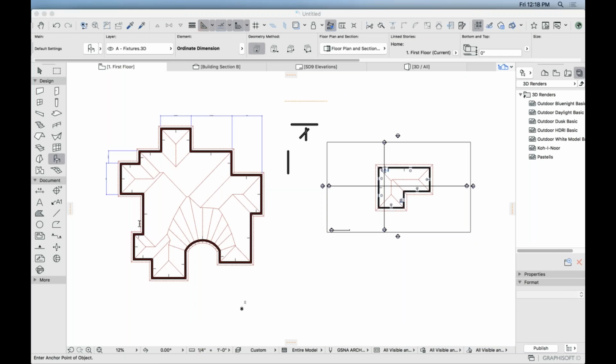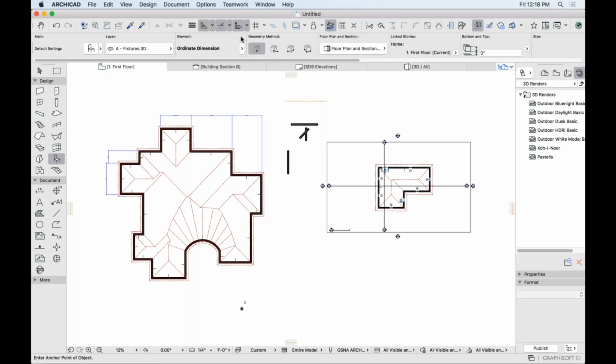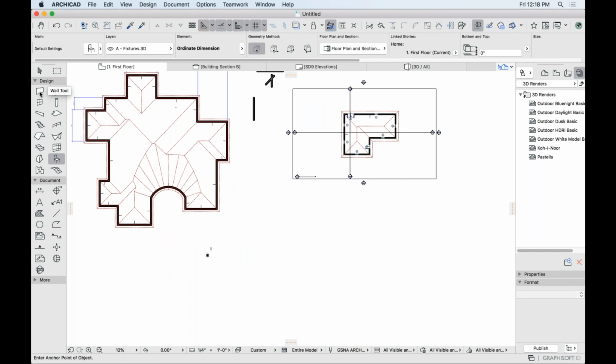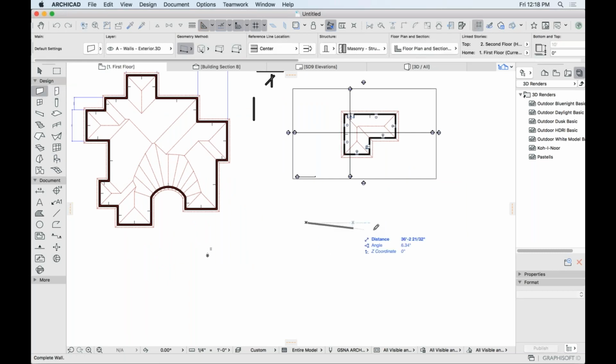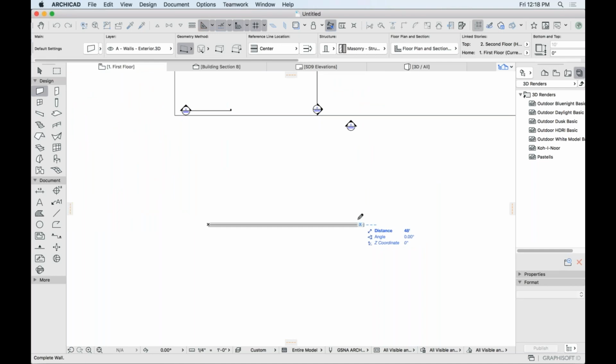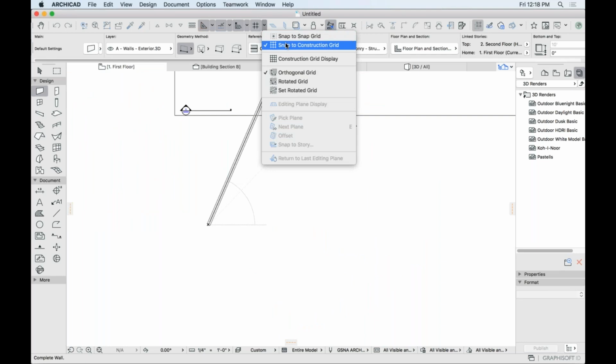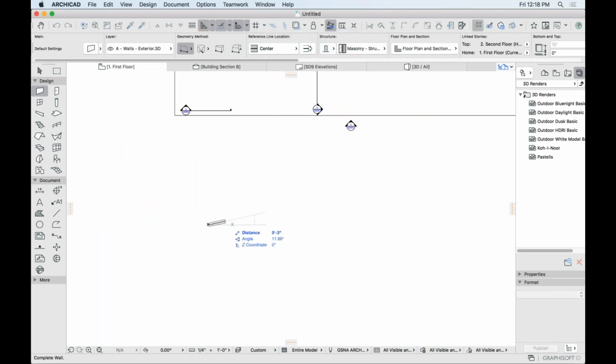What allows you to draw a wall at varying angles? Mine defaulted to 0 angle. If you have the snap grids enabled, then it's going to restrict your angles a bit by its very nature that it's snapping to a grid. In my case, mine might be loose enough that I'm able to work along those various angles. Depending on the settings you have in your snap grid, it might be set in such a way that you have a very limited range.